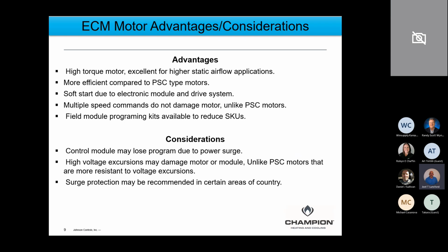The ECM type of motors, they'll actually sit here and rock a little bit when they start up, and that little rocking action is normal. What that's doing is finding its rotor position, but it's also decreasing the starting amperage on that motor. And we like to call that a soft start. So it's really a soft start situation that makes it easier on the motor to start it up, and it also reduces that inrush current, or the amperage, to get that motor started.